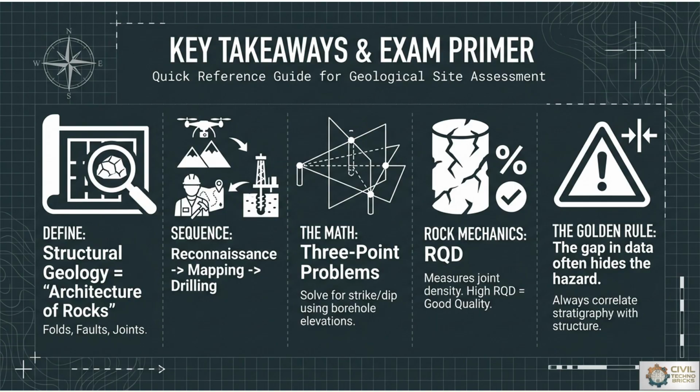We collect the samples by using some drilling methods to check the RQD, that is rock quality designation, which ensures engineers can take the decision for the suitability of foundation for any dam or tunnel, which measures the joint density.